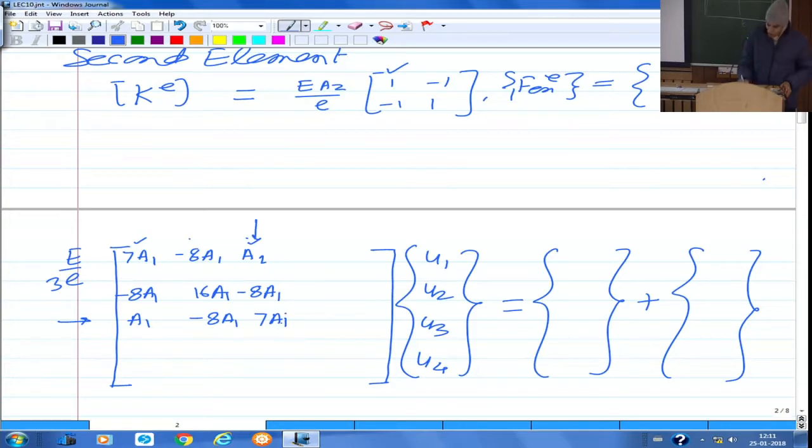So that is here, which is basically A2, and since we have taken 3 out, let me just write that as plus 3A2 here, and then here we'll have minus 3A2, and then the second row will go to basically fourth row, columns 3 and 4. So we'll have minus 3A2 and 3A2 here. If you would have taken this 3 inside, it would have been in the division here, and then this is simply plus A2, minus A2, minus A2 and A2. And wherever we don't have any contribution, those terms are actually 0. So this is 0, this is 0 here, 0.